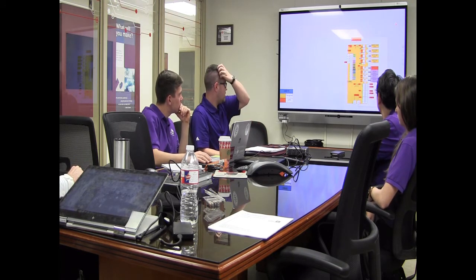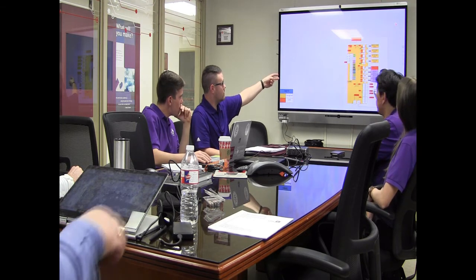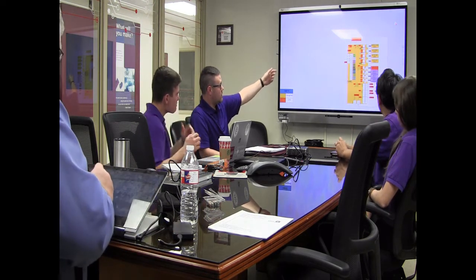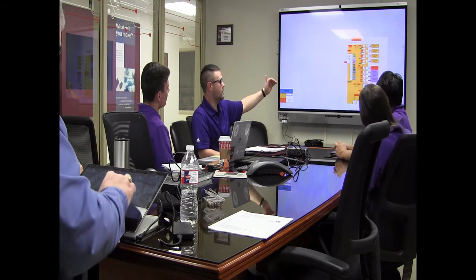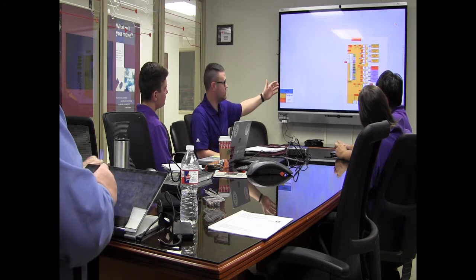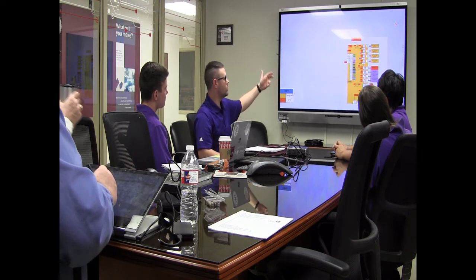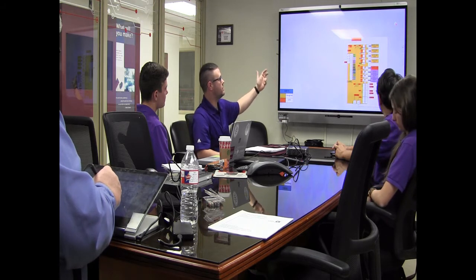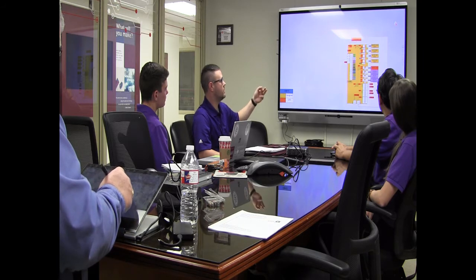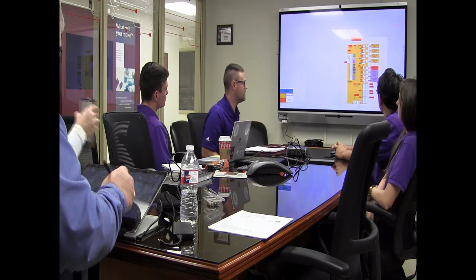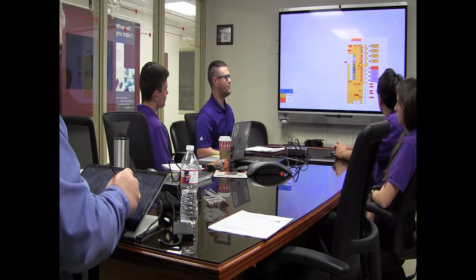And then, like Abby said earlier, 2 PWMs are going through low-side switches up to 4 different ports. So we have examples of what you could plug in. This is an exact representation. You could actually run 2 servos per RJ12, 6-pin, 6-conductor straight-through cable out to 2 individual servos, which we have like window shades, air plenums, motion sync, door locks. Some of them are dualed up because we don't just have one thing plugged in. We'll have 2 shades, 1 on each channel,